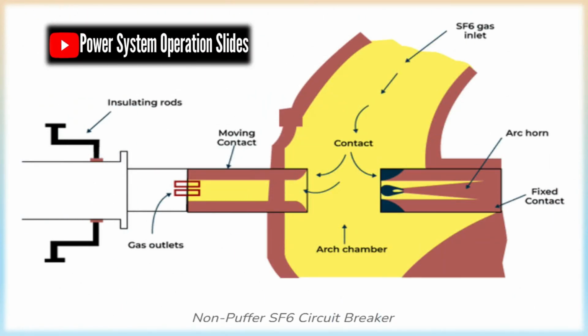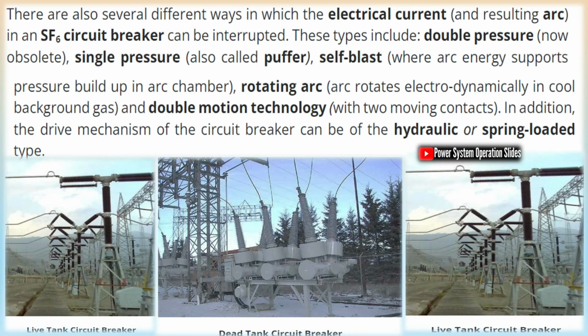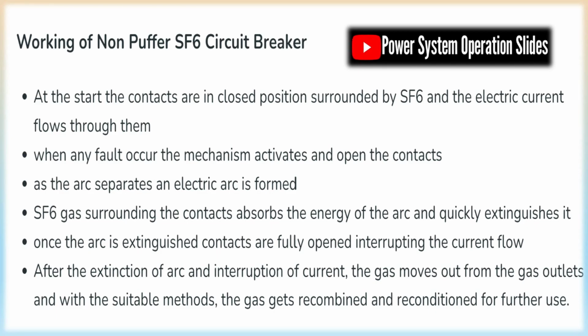The working principle of an SF6 circuit breaker involves the use of pressurized gas to extinguish the arc. Under normal conditions, the breaker remains closed, and the SF6 gas serves as an insulating medium. During a circuit breaker opening operation, when a fault is detected, the operating mechanism separates the contacts, an arc is formed and immediately quenched by a blast of SF6 gas directed through a nozzle. Once the arc is extinguished and current reaches zero, the breaker fully opens.